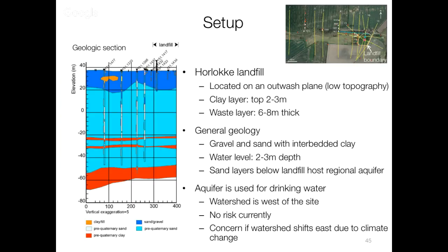So the general area is that we've got sand and gravel kind of interbedded with clay. The blues here are sands and gravels. These reds here are clay, and so you can have water that's in these areas, and you've got some aquitards. As far as the waste deposit goes, it's probably 6 or 8 meters thick, and there's a clay layer on top that's a couple of meters.